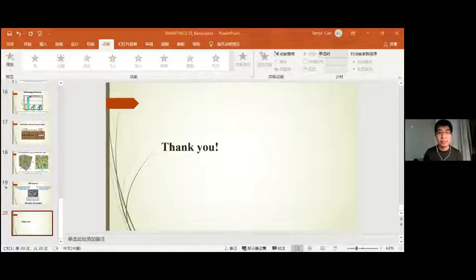The lightest density is, of course, the voids and the cracks, so that's the density of air. And then we have a medium density of swollen SAP that is basically similar to the density of water. And we have the heaviest phase, which is cement bentonite, the cementitious matrix. Based on the difference in the densities, we can tell apart these three phases, and then extract a certain phase that you would like to investigate.